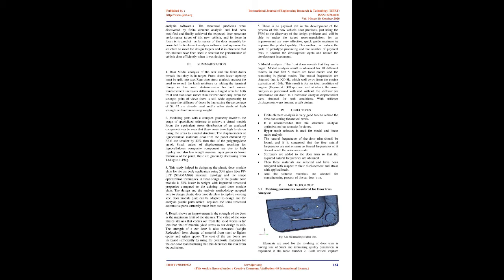The remedy is to find the maximum absolute value out of the two at the point over a given period of time, and then find the stress range or amplitude and mean stress based on this data. Say the maximum principal stress at a node at time 1 second is plus 250 N/mm2 and the minimum principal is around minus 400 N/mm2, then the absolute principal stress is equal to minus 400 N/mm2. Collect the data over a period of 10 seconds and then find the stress range based on the maximum and minimum absolute stress values out of the 10.